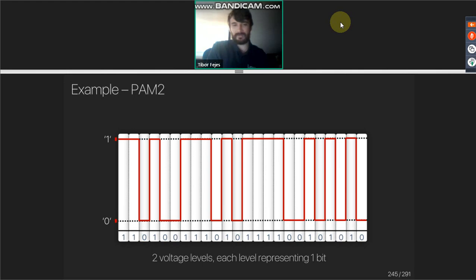To compensate for that, the swing has to get faster and faster, and that's where you start to come up against issues that increase exponentially. To increase the speed by double, let's say, it's going to take 4 times as much energy and generate much more noise. So the power increase and the EMI generated increase exponentially.